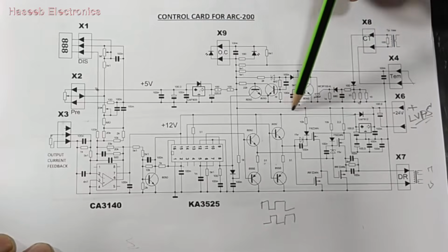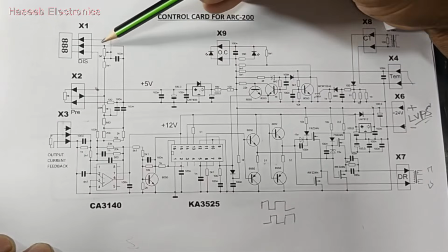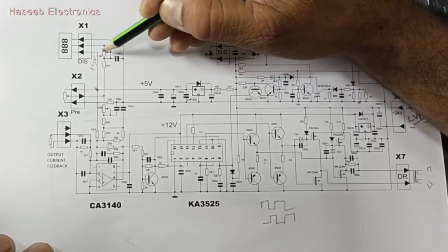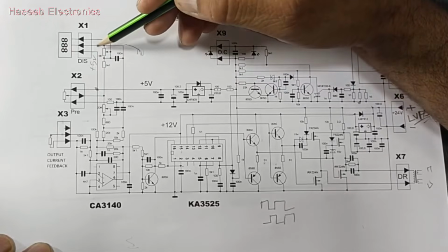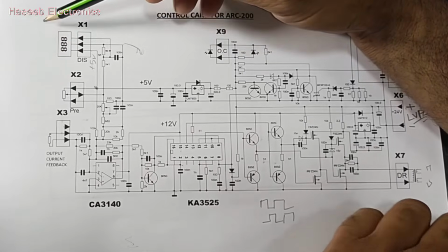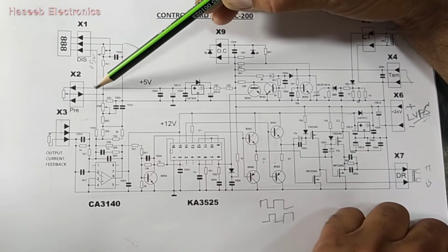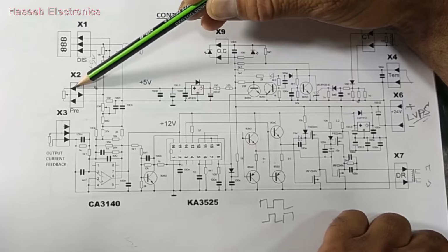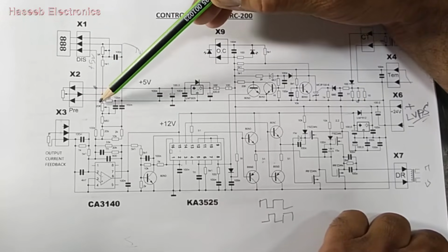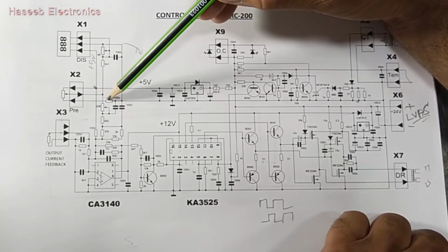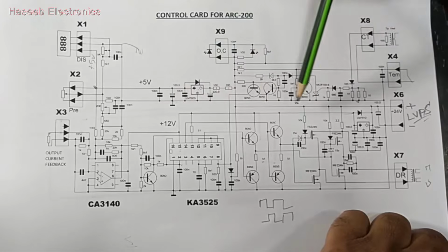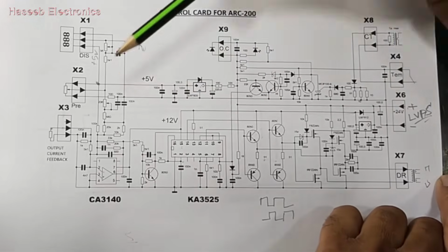We applied positive 5 volt and ground, so this display meter will be energized and ready to take some measurement. Positive voltage is applied to one side of the potentiometer, and the last end of the potentiometer is connected through this 100 ohm resistor to the same ground line. This is the 24 volt ground, the low voltage power supply ground.